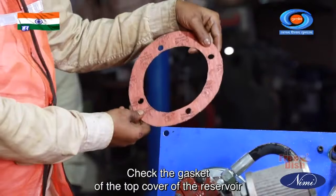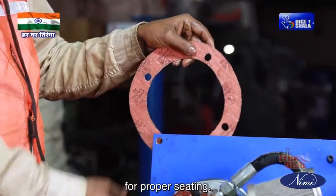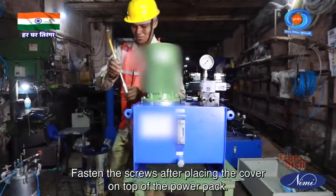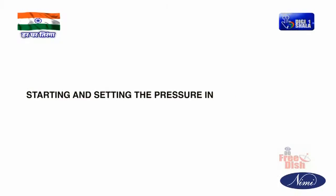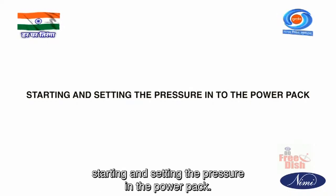Check the gasket of the top cover of the reservoir for proper seating. Fasten the screws after placing the cover on the top of the power pack. The next thing we need to do is starting and setting the pressure in the power pack.